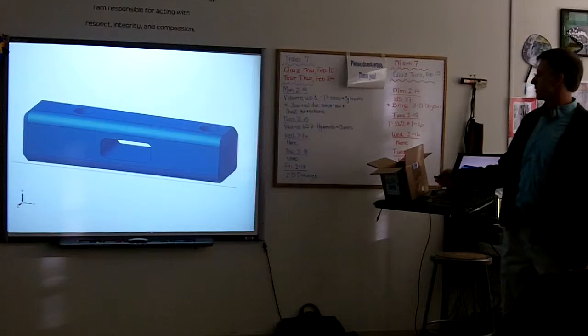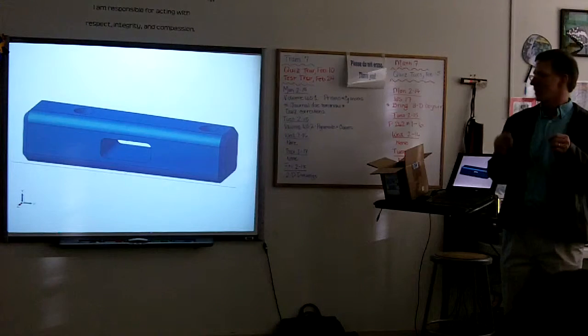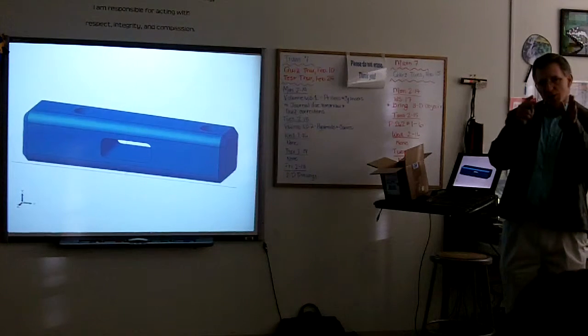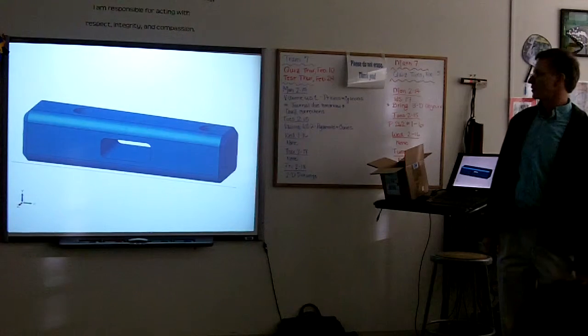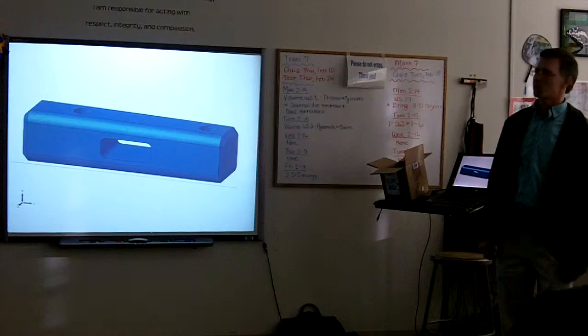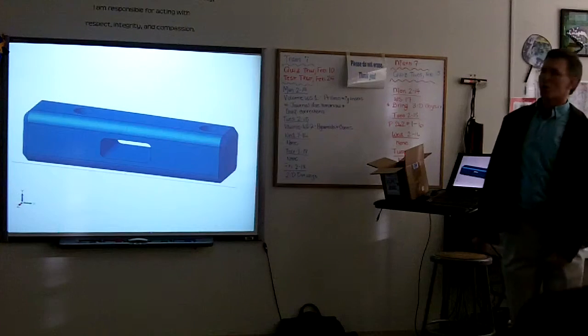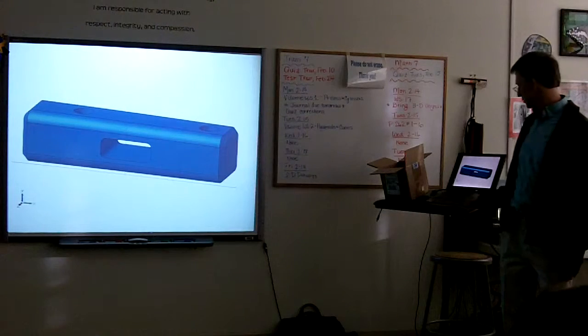And similarly, if you wanted to make this hole bigger, you just say, okay, instead of that hole being a 1/4 inch wide, make it an inch wide. And you go back to that sketch, you just change that dimension, boom, it does it. So it's very fast. Now I like being an engineer. It's very simple. You spend less time having to create the drawings and the models and more time actually thinking about the design and what you want it to do.